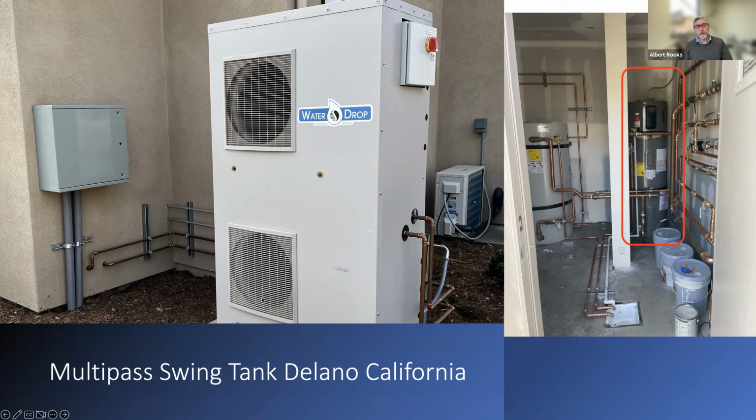You can see the room has a lot of copper showing, though of course it gets all insulated, and this building has a full M&V kit on it. So we're going to see every bit of water used, and all the energy associated with that water used. That makes the piping rather expanded, because you have to have room to place all those flow meters and the BTU meters and things like that.